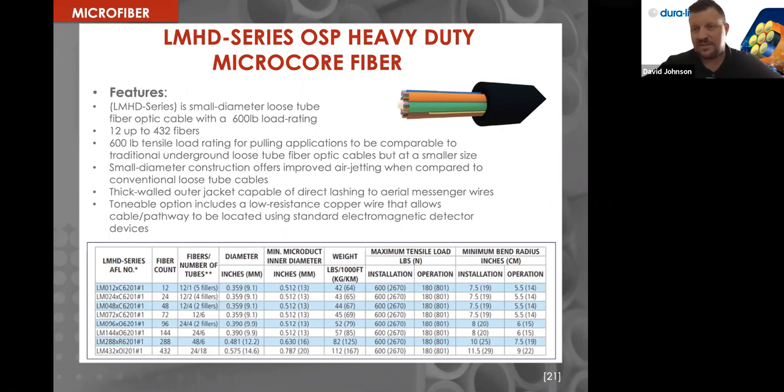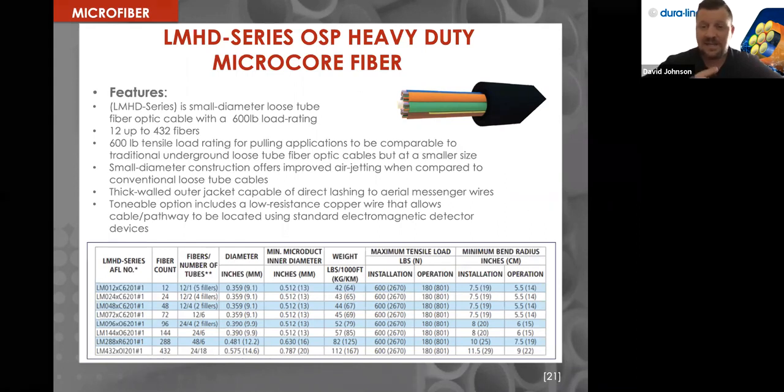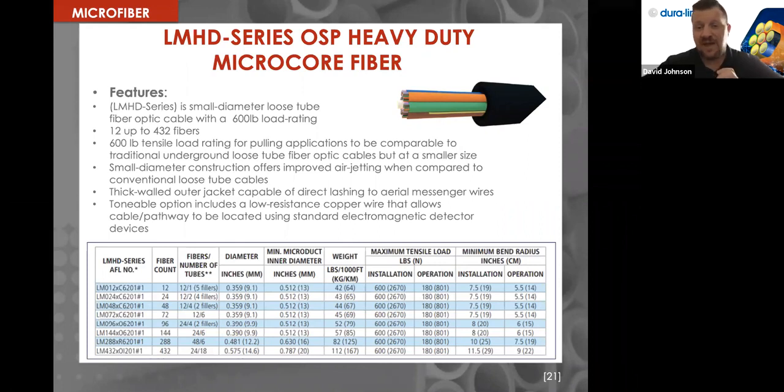So I'm going to take an easy calculation here. And I'm going to go with a 1410 microduct, which is the ID is 10 millimeters. So that fiber cable would have to be 5 millimeters to 7.5 millimeters. That way, you're going to be in the best situation for you to have success in jetting and blowing that micro cable into the pathway. So just remember, 50 to 75% fill